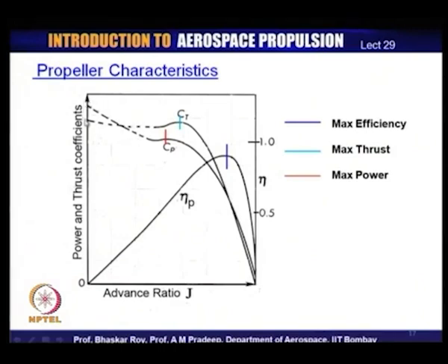However, you would probably get maximum performance at the takeoff point. So, during the takeoff run of an aircraft, maximum thrust and maximum power would be created, and then of course, it would go through the climb procedure, and then you have the flight, during which the propeller characteristics are more clearly available. During the climb phase, the propeller characteristics may be slightly uncertain, using this momentum theory that we are talking about, and you may need slightly more advanced theories to calculate what is happening during the climbing operation of an aircraft.